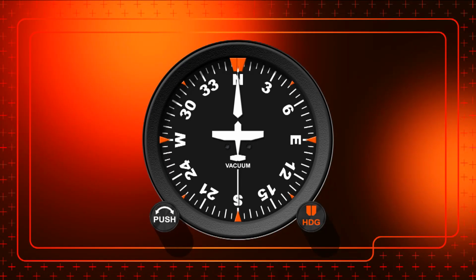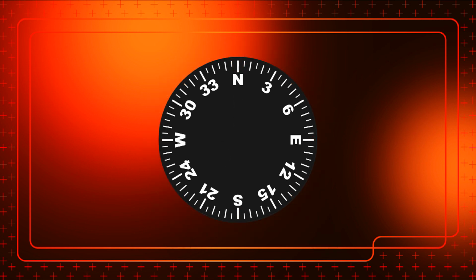The heading indicator gives the pilot a heading reference that the aircraft is flying in relation to the magnetic North Pole. We will now go over each of the individual parts of the heading indicator's display and explain what they represent to the pilot. We will start with the compass rose, which as you can see is made up of a series of scale markings in differing lengths.